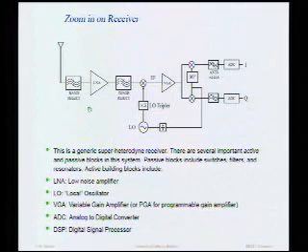One reason is that this receiver, basically using this mixer, first thing it does is it downconverts the spectrum down to a fixed IF frequency. IF stands for intermediate frequency. And we basically do some signal processing at the IF frequency, and we then digitize the signal. So the ADC here is analog to digital converter.